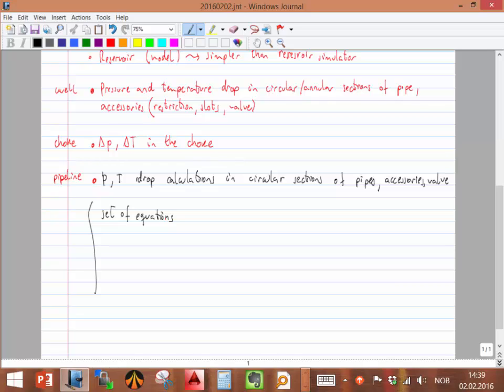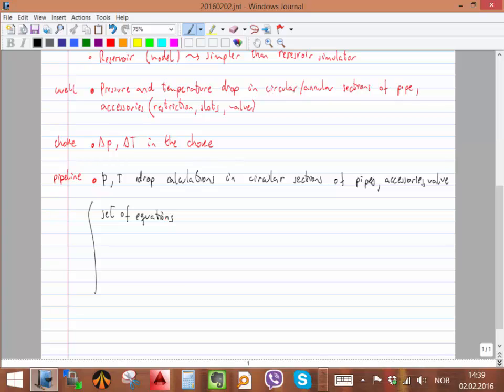Like you will say, someone whispered now that you use friction, okay? Do you need friction? You calculate friction in these expressions. What do you need to calculate friction? You need Reynolds, and to calculate Reynolds, what do you need? Flow rate, but before flow rate, so we have the flow rate, okay? Let's say that you know the well is producing a certain amount of oil, but that is a volume, okay? So how do we convert it, what do we need to calculate Reynolds number? Yeah, we need viscosity. So viscosity is a fluid property, okay? So we need a calculator that allows us to calculate fluid properties also in this system. So we have a set of equations for delta P, for delta T, and we have also something that tells me how the fluid is behaving.